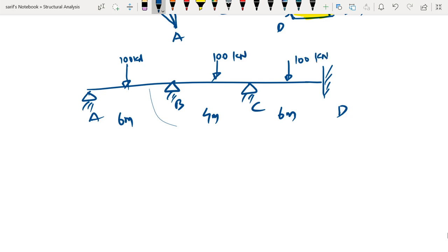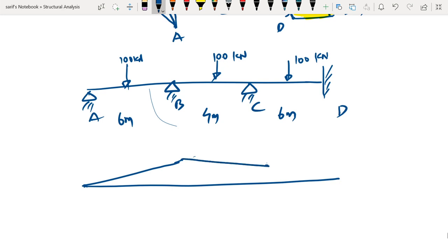Now the method of solution, the moment distribution table, and the answer will all be the same for this. The only difference is that this is a beam and the other one is a portal frame. Now how do we draw the bending moment diagram? We have 81 here, a 55 here, and an 85 here, and then you superimpose it with the simply supported bending moment diagrams.